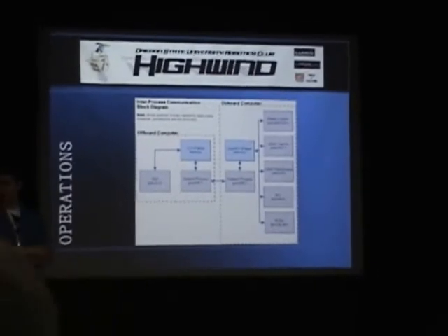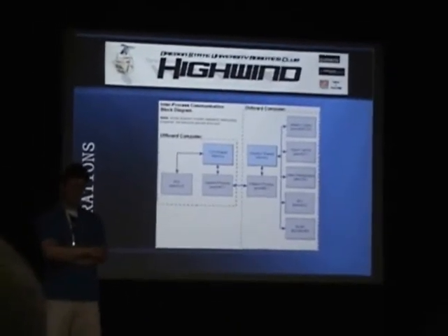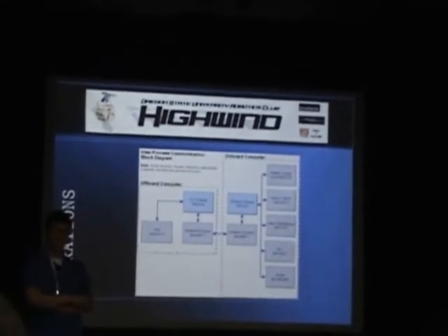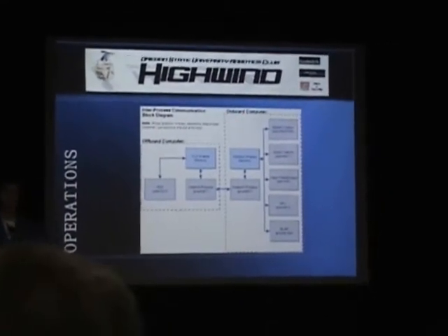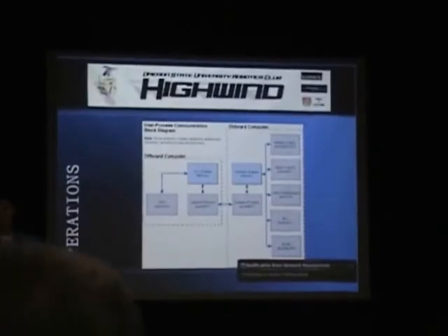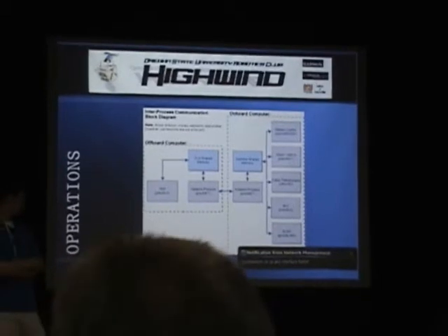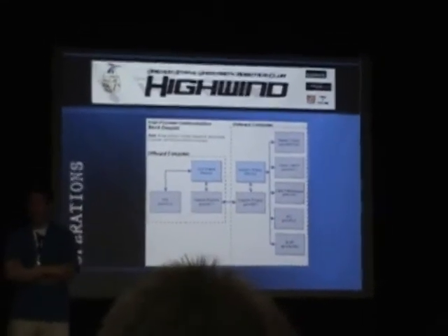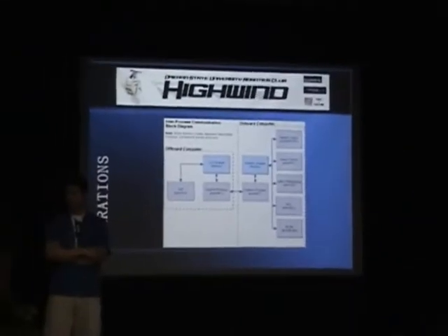in order to allow, for example, if we wanted to run SLAM off-board or if we wanted to do stereo vision off-board, the 802.11n gives us the bandwidth that we need to be able to pipe all that data off-board, and then heavy computations can be run on another computer and can then be sent over to the gumstick without it having to do too much overhead.